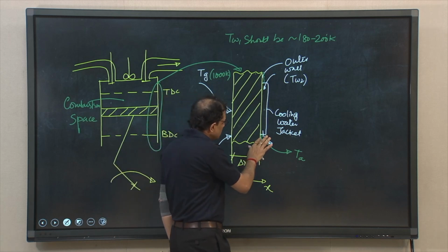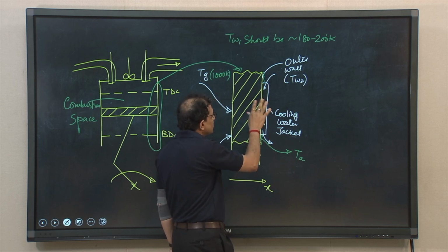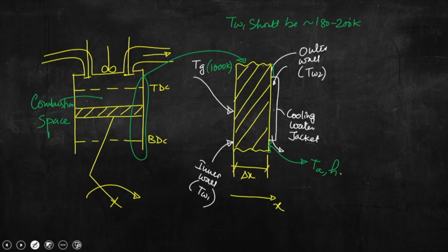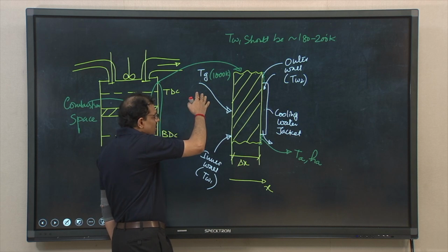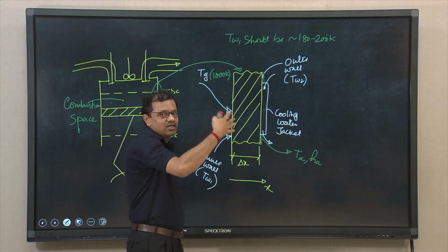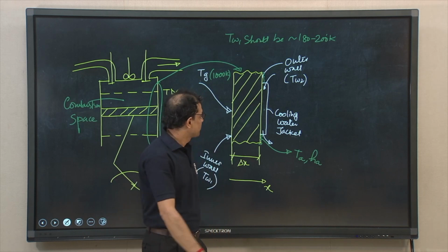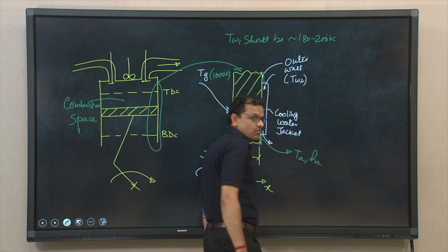The convective transport of heat from the portions not in contact with the coolant will depend on the ambient air temperature and the convective heat transfer coefficient of the ambient air. So, these are different modes of heat transfer inside the combustion chamber. Again, since the temperature of the gas is too high, we really cannot trivially ignore the radiative transport of heat, which is solely due to the very high temperature difference. So, this is all for a water cooled engine.